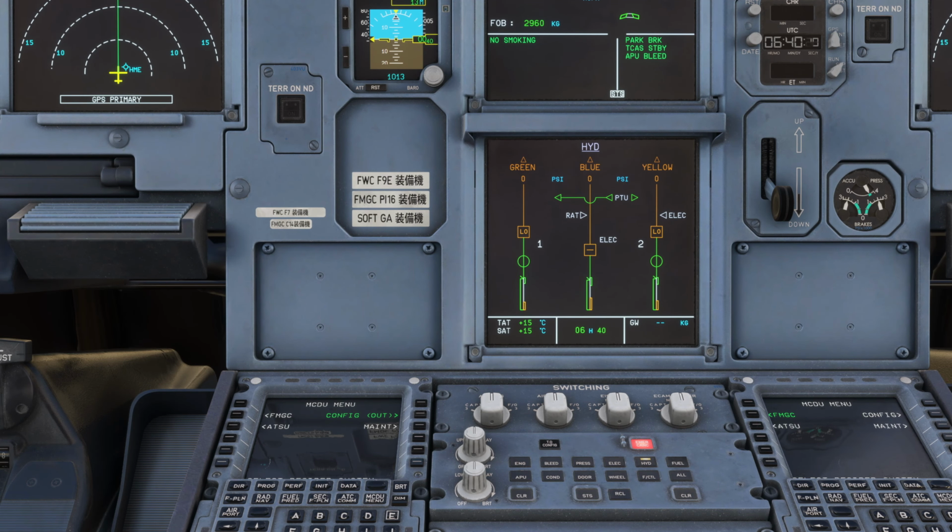The A320 hydraulic system is comprised of 3 continuously operating systems called yellow, green, and blue systems. Each has its own reservoir and fluid with no fluid transfer from one system to the other. They are completely independent. The power for the green hydraulic system comes from the engine-driven pump on number 1 engine. It's pressurized to 3000 psi. The yellow system is pressurized by engine-driven pump on engine number 2. It can be powered in a number of other ways too.